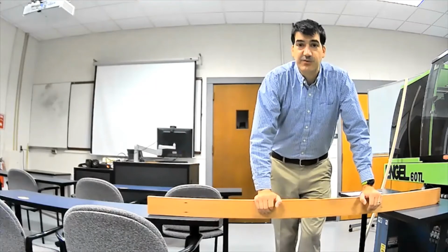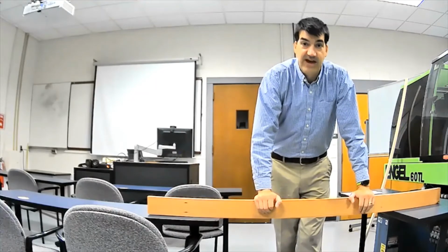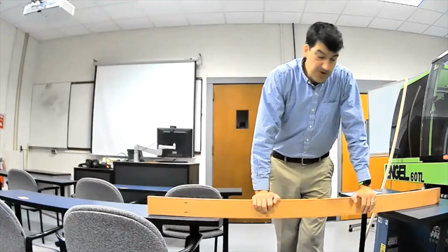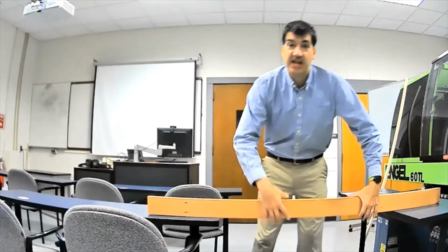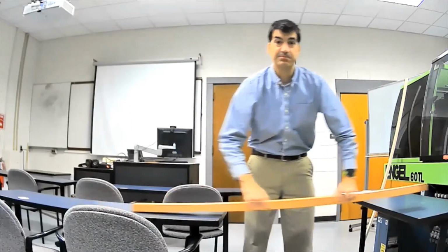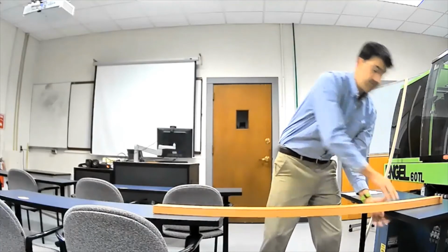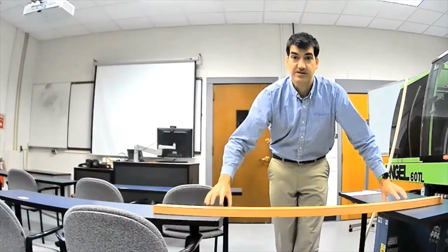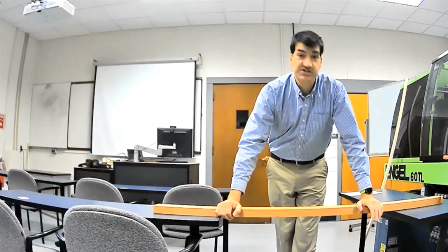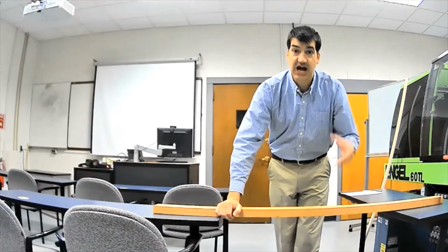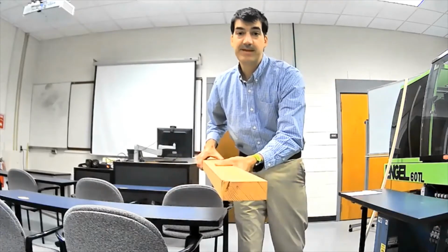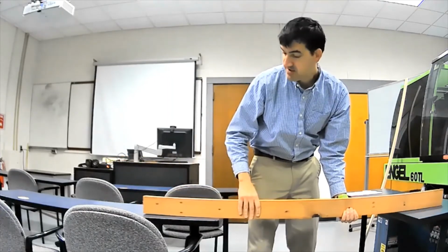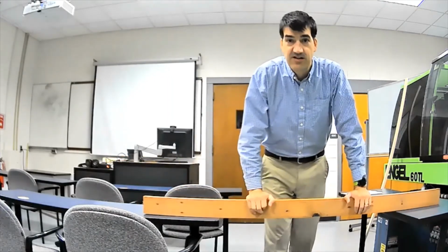So what are the things that we talked about just now that we said could affect the amount of force the beam can support? So in no particular order, we said that changing from a cantilever to a simply supported to a fixed on both ends, clamping down on both ends, that would change it. That's the way that we support the beam. We said that changing the moment of inertia, which is the geometry of the beam, even the same beam going from horizontal to vertical, that changes the moment of inertia of the beam. So that's like the geometry of the beam.